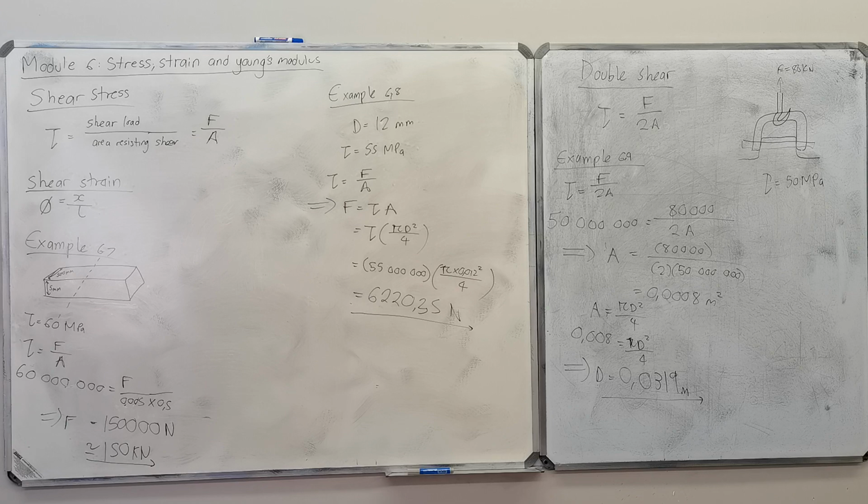But won't you now work it out with the smaller diameter because that will give way first? Not necessarily. The force would still be distributed equally amongst both sides. It's just that the smaller diameter shears first, because it holds a lower surface area. It depends what you're asking for: the diameter, the stress, or the shear force? If it's what will break first, the smaller one would break first because of the smaller area, so you use the smaller area.